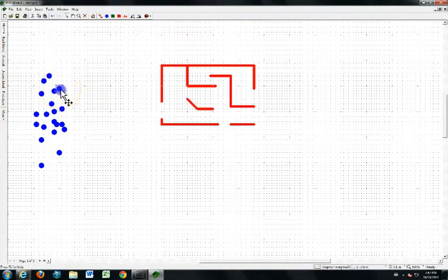I can now come over and click on these pads that I stockpiled earlier, and I can just drag them into the location that I want them. How do I know where to put them? Well, I'm just following my diagram that I've already drawn, and I'm looking at my drawing in front of me, and I've already got the parts labeled, so I know what parts are going into each pad. Just like the way we taught it in class.